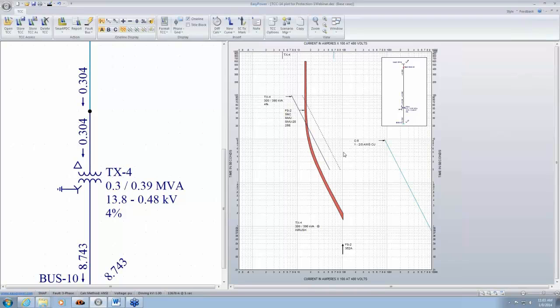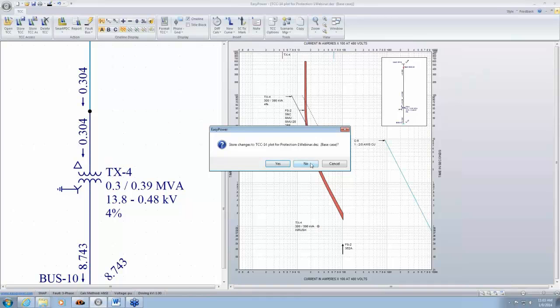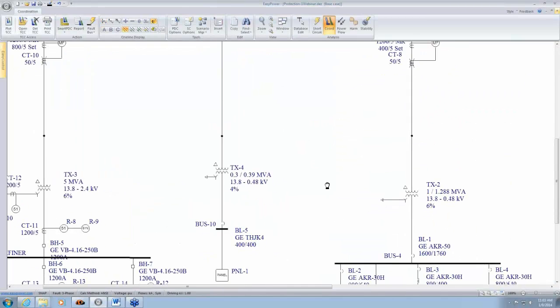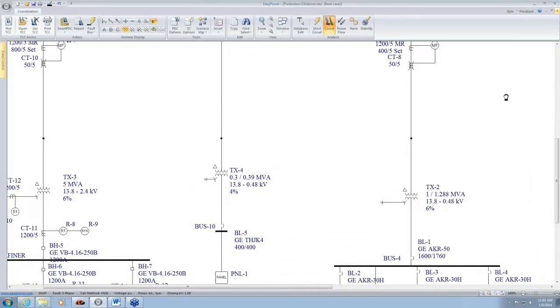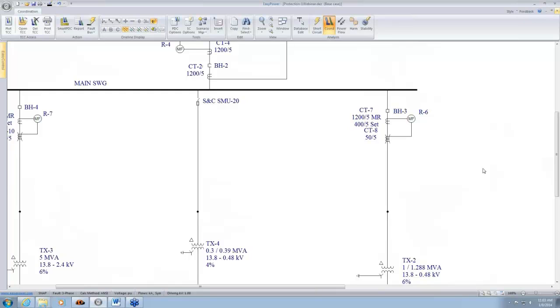Okay, now whether you choose fuses or relays, the protection principles are very much similar. You have to watch out for the damage curve, and you've got to watch out for this inrush current. Okay, so we talked about motor protection, cable protection, and transformer protection. Next, we're going to talk about selective coordination here.